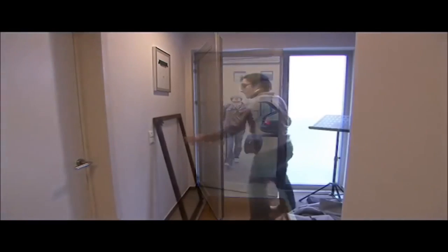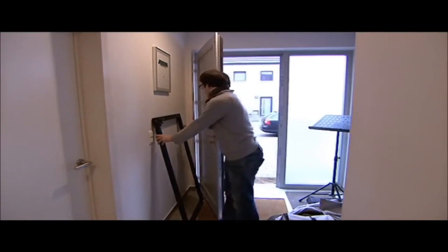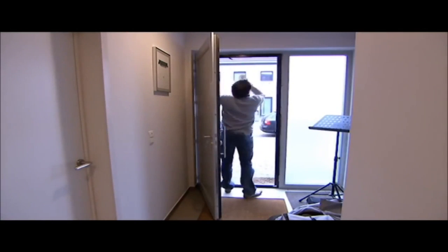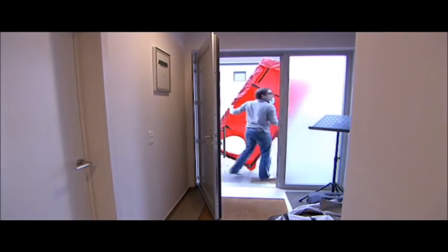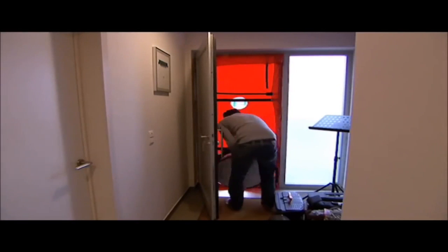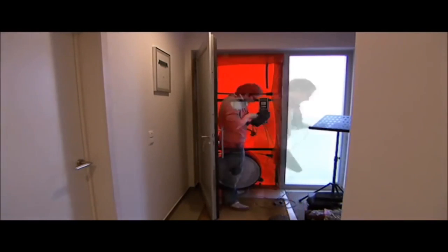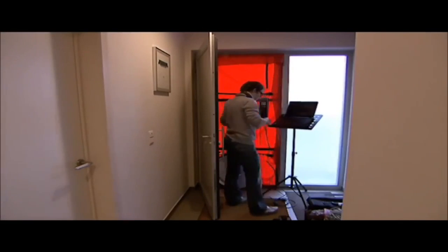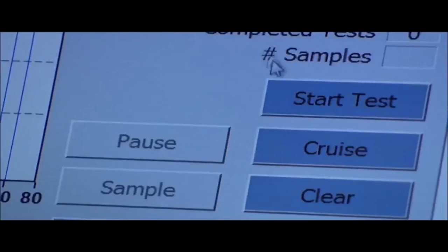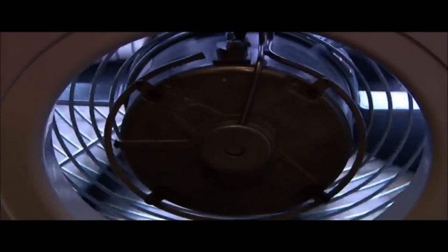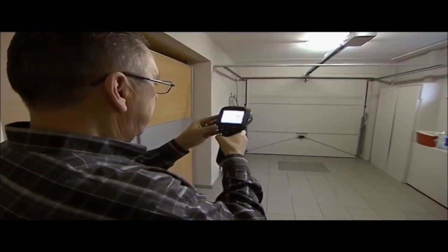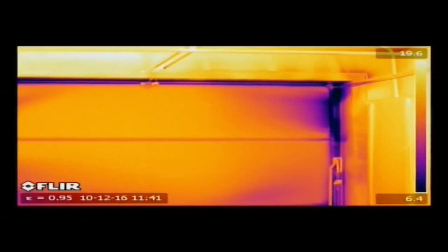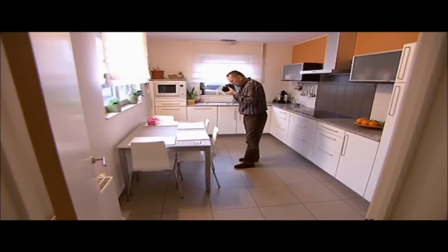Thermal imaging can also be used inside buildings. Air leaks in buildings can be visualized by identifying the air change rate with the help of what's known as the blower-door process. This process creates underpressure in the building. Since the air pressure outside the building is higher than the pressure inside, air will try to enter through unsealed areas. Air leaks can easily be visualized with a thermal imaging camera. Thanks to thermal imaging, there's no need to fill the room with smoke to visualize the airflow.